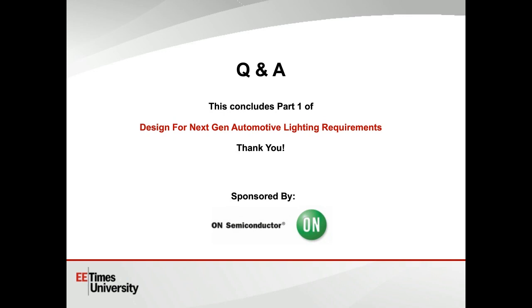Or could they drive it with more current? Increase the drive current to that LED. They could increase the current output. The problem with increasing the current output is you increase the temperature, and as we'll see later on, the failure rate of LEDs increases tremendously as the temperature goes outside the maximum. But yes, I suppose you could do a little bit of compensation, but you can't do too much for thermal reasons. I think that would be a pretty slippery slope beyond a relatively small window.